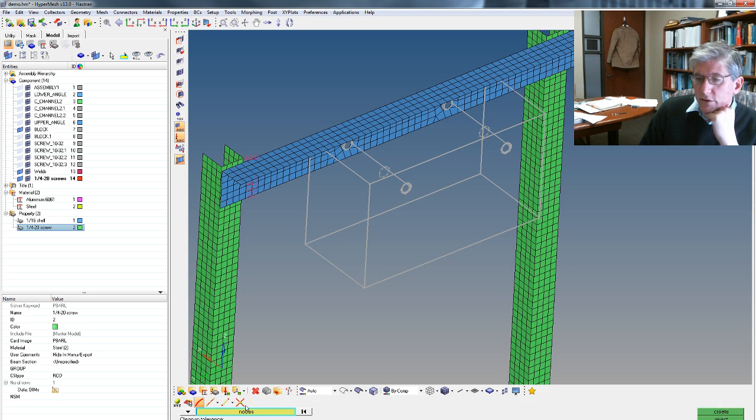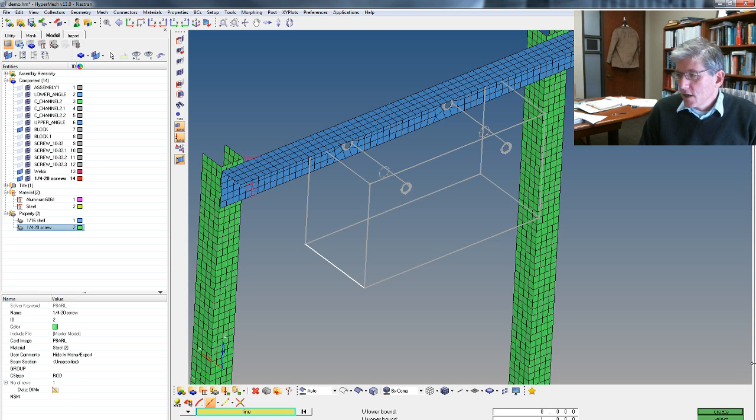So we'll use geometry nodes, and we'll actually end up using this function, which allows you to interpolate between 2 different nodes. But before that, I need nodes on the edge. So this one will allow me to put nodes on an edge. So I can do 2. I think that'll work. So we'll click this edge, and we'll create 2 nodes on that edge. And we can do this and create 2 nodes on that edge.